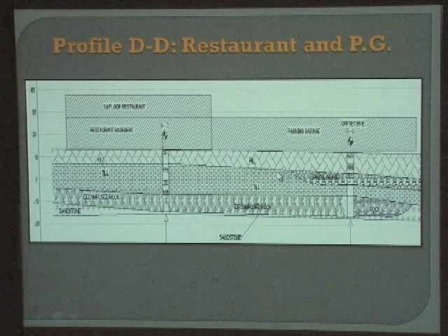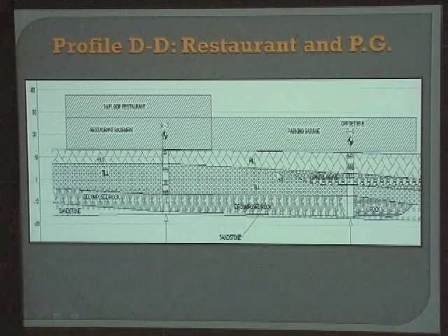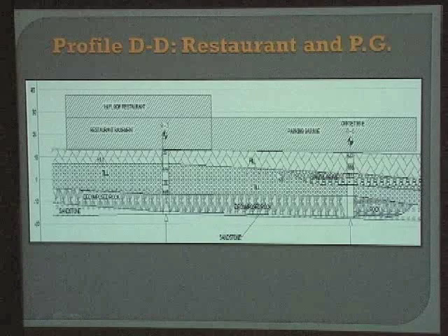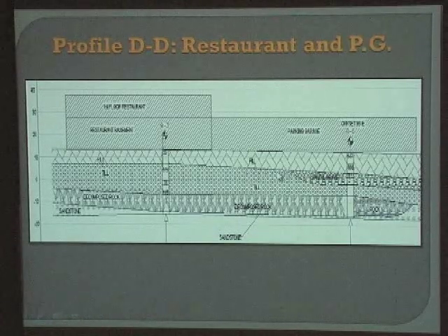Our parking garage has a similar situation. It also has an elevation of 13 feet. This will require a foot of fill added on the south end and 2 to 3 feet of fill added on the north end. Below this added fill is 8 feet of pre-existing fill with blow counts of up to 150, which is described as a very dense soil. Below this is 5 feet of very dense sand and gravel, followed by 5 feet of very dense till.